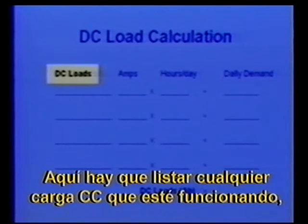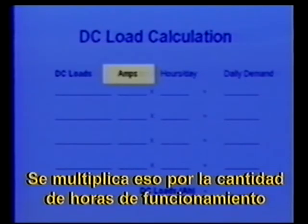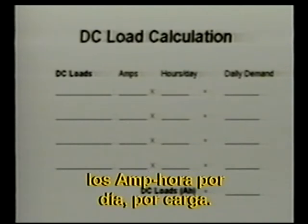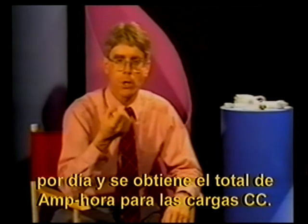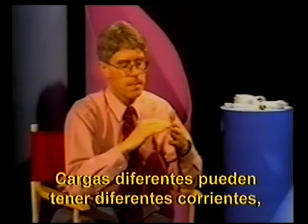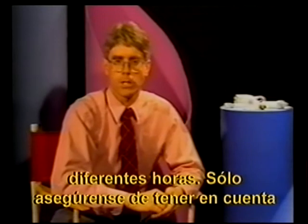Here you want to list out every DC load that might be operating, the current draw that it might draw, how many amps, multiply that by the number of hours in 24 hours, in a typical day, that it might be operating. And multiply that out, you get amp hours per day per load. At the end of the column, you'd add up all those amp hours per day, and you'd end up with a total amount of amp hours for your DC loads. Different loads might be different currents, might be different hours. Just make sure that you look at each and every load that might be operating.